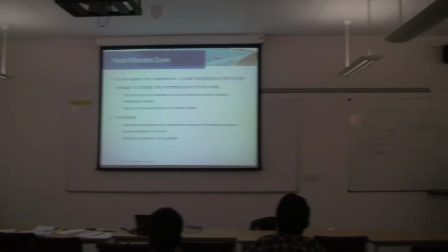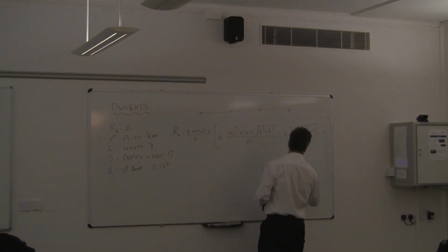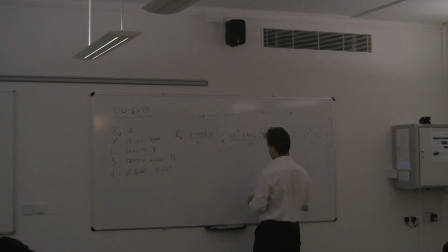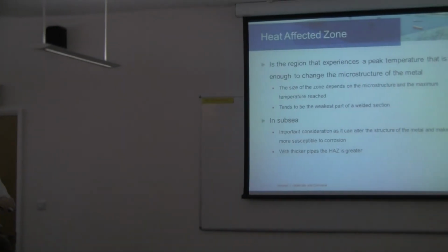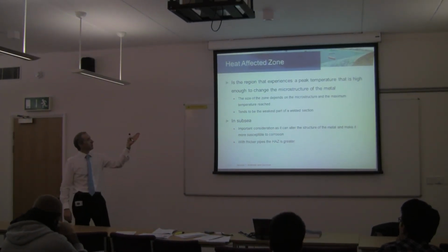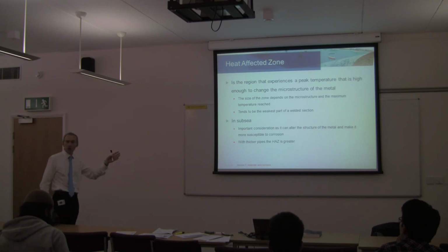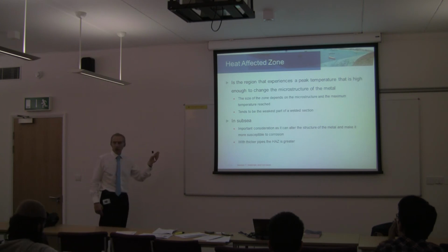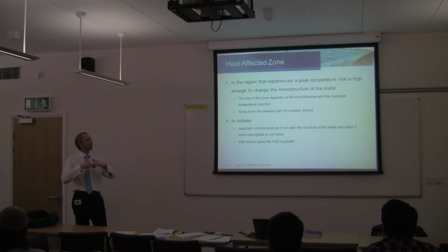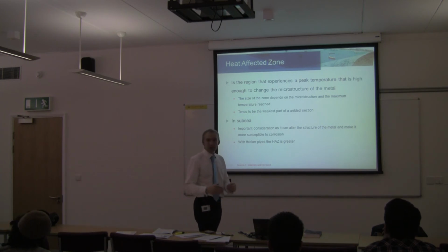Okay, right. When you're welding two pieces of pipe together, the heat is obviously going to spread through the pipeline, heat transfer through the pipeline. That's called the heat affected zone. It's enough to change the microstructure of the steel, and that can have all sorts of consequences on corrosion, weld corrosion, and also the strength of the pipeline as well. If you're changing grain boundaries and the microstructure, the pipeline can become more brittle, and eventually that leads to weld failure.